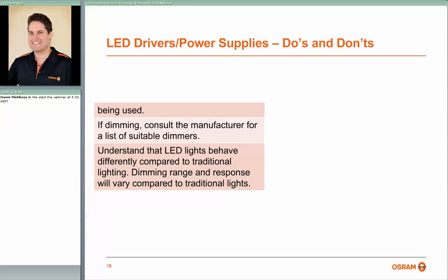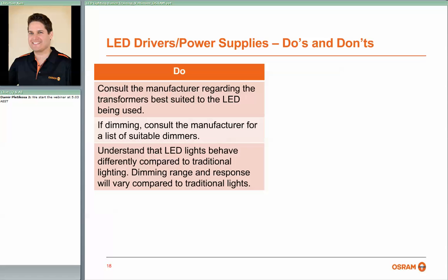So some of the do's, and it's always an important and pretty obvious one, is to consult the manufacturer regarding the transformers or drivers that are best suited to the LEDs being used. If dimming is required, then consult the manufacturer for suitable dimmers. So going through those two points, the reason why that's important, particularly with the LED lamps or retrofit type